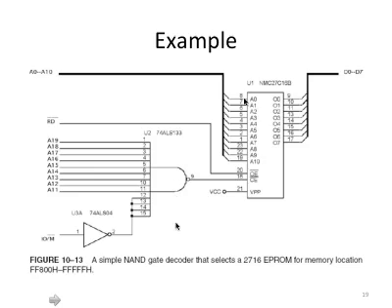The rest of the input pins of this NAND gate are connected to the remaining 8 address pins. And the output of this NAND gate is connected to the chip enable signal.